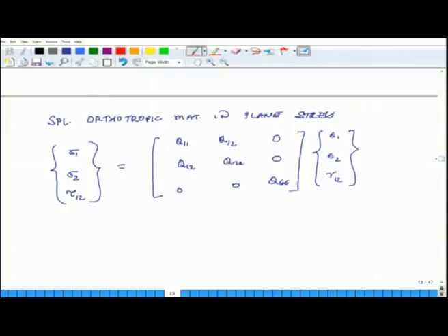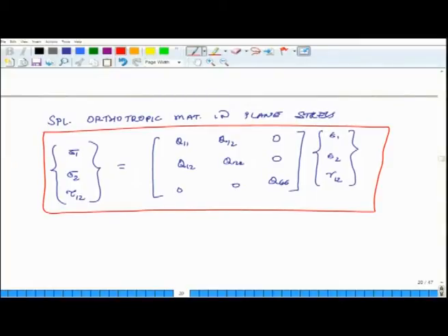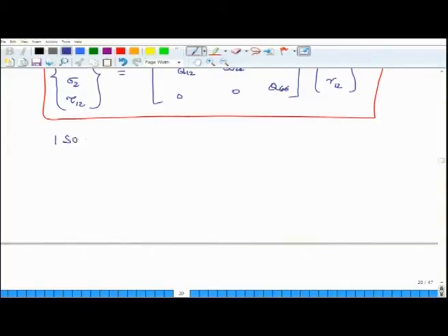So, these are the relations for especially orthotropic materials. Okay. And then finally, for isotropy, we have 2 constants, and we will not discuss this because we are short on time and the focus of this course is on orthotropic materials. So, we will not talk about it, but in general E and mu are considered as 2 independent constants. All other constants, shear modulus, bulk modulus can be expressed in terms of E and mu. So, let us have a quick summary.